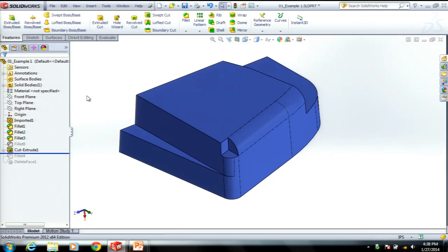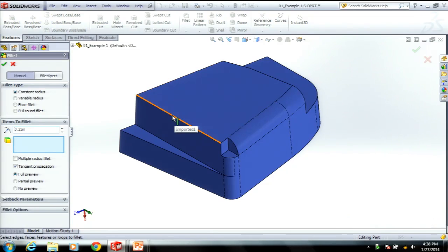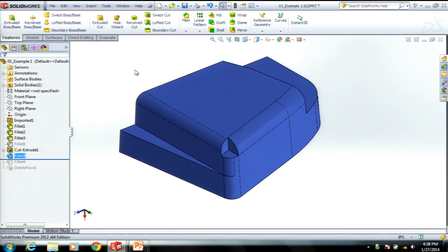So I'm just using a simple cut extrude. And then what happens when I go to add my 1/4-inch, not 0.22-inch fillet? Preview. So I've been able to add the fillet to the model. But you may ask, well, now you have the corner cut out of the model. How are you going to resolve that? Well, I'm going to use the delete face tool to do that.